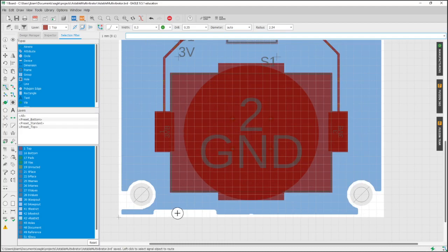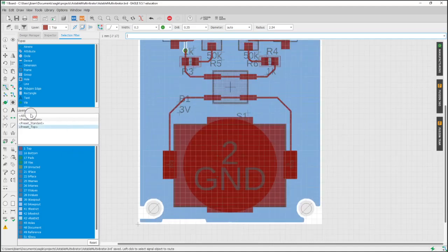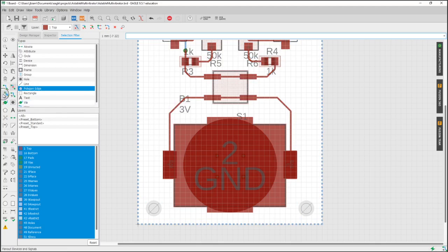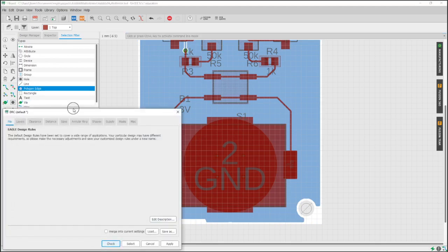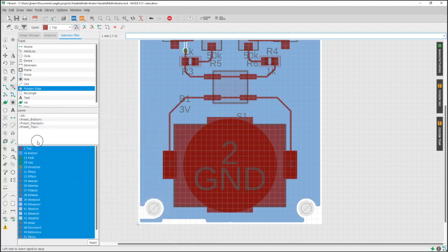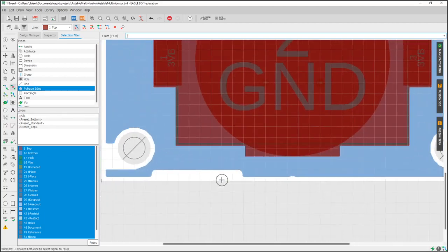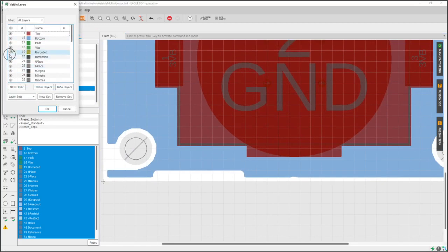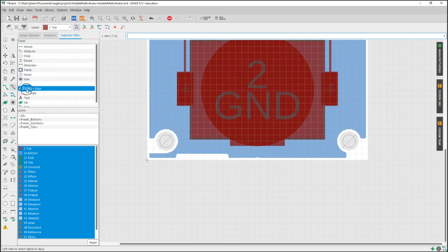Also, you can see here that there's something interfering with this pour because a piece of that shape is taken out. And it's still doing it, so I'm going to have to troubleshoot this for a second, figure out what's going on. Oh, now I know what it is. It's the dimension. So you can see those dimensions are actually affecting the ground pour.